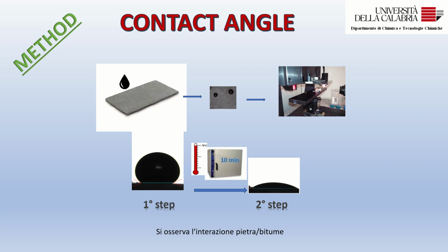And we use this technique, the contact angle, to determine the affinity between the aggregate and bitumen, or the polarity of the bitumen. In this slide we show the procedure that you use to realize the contact angle, the preparation of the sample to determine the affinity between stone and bitumen.